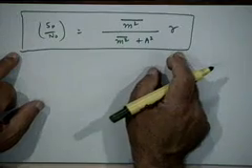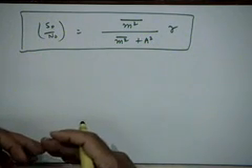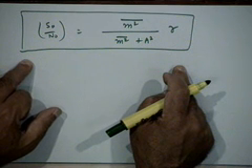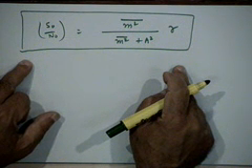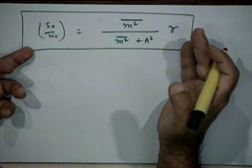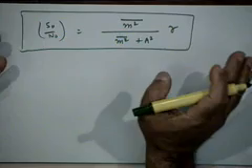Now what is the difference? Whereas for synchronous demodulation, this expression is valid irrespective of the input SNR, for the case of the envelope detector, this expression is valid only when the input SNR is sufficiently large. Is it clear? What happens otherwise, we don't know, we have to find out. All we are saying is that the assumption we made in the analysis is not valid, and therefore this expression will not be valid. We will not be able to calculate the output SNR using this expression. That's all we can say. Whether it will be worse or better, we don't know. We have to find out.